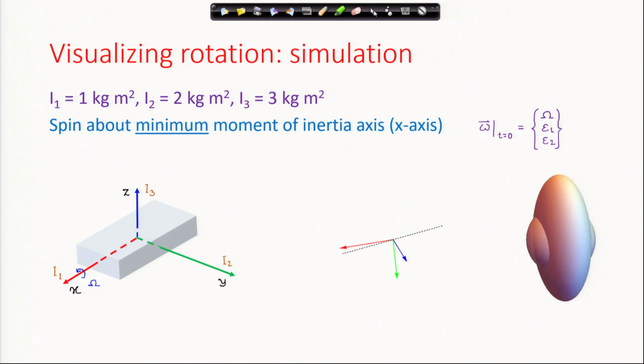And you can see the Poinsot construction, the intersection of the angular momentum sphere and the energy ellipsoid, is like this. Here, if you note the precession, it is direct precession, and the angular velocity is this. To change values of the lowercase hx, hy, hz, the frame has to reorient, and this is direct precession.